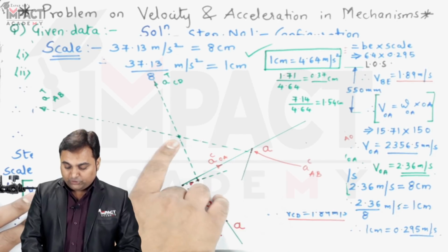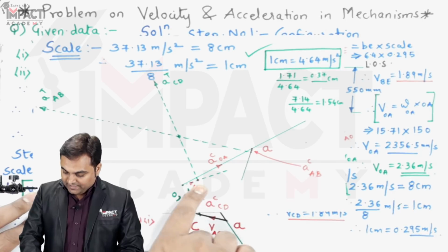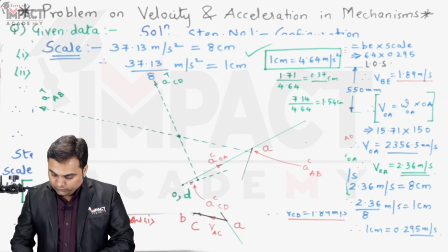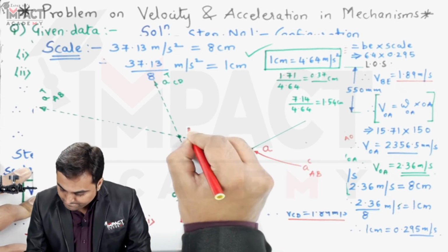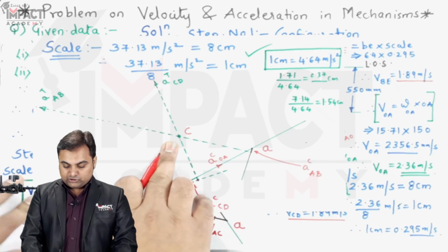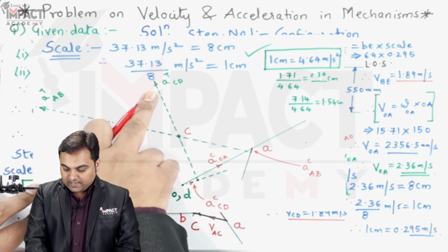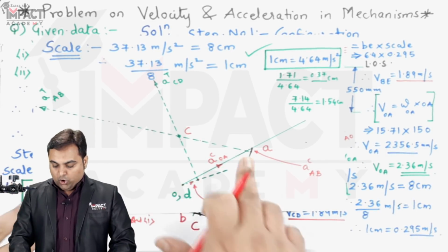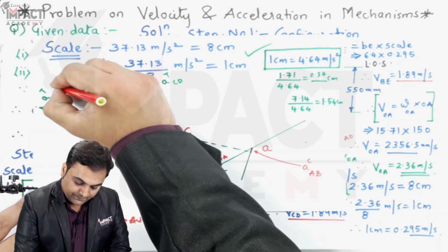Actually, I would be getting point C here. Remember, because here we have point D, and then this would be representing, I'll just show it here. We are getting point C here and not point B, because at present the intersection of CD and this line, which is the tangential acceleration of AB, also the tangential acceleration of AC is along the same line.